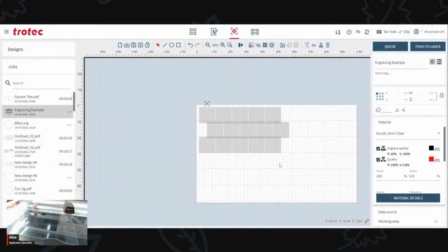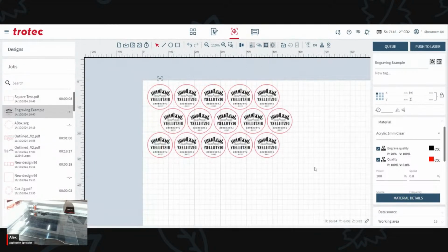I can click update. And then, for example, if you want to know the full runtime before you run a larger engraving job like this, you would use calculate job time. And once that's run through the process, of course, you have to have the right material setting here. You can see it adds it to the right-hand side of your job. So if you've run a job previously, it automatically updates and stores this data here, so you know how long it would take if you need to run it again. Using this method, you can see we have the time for the engraving in here as well.